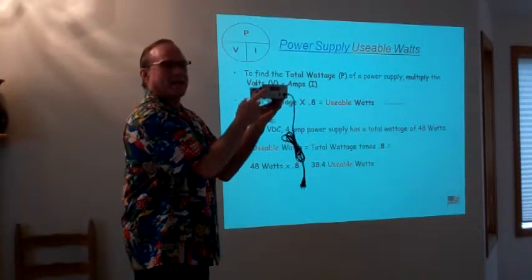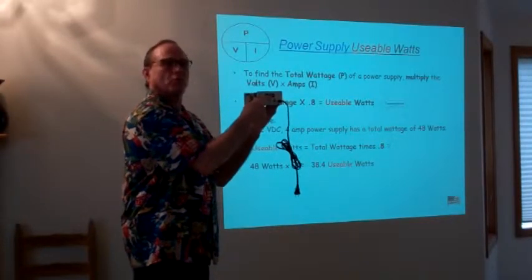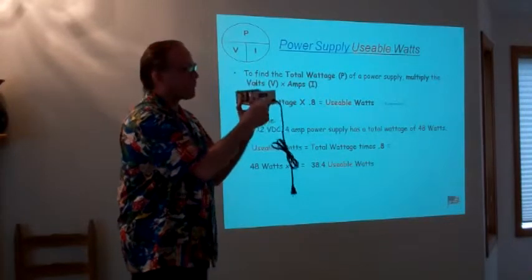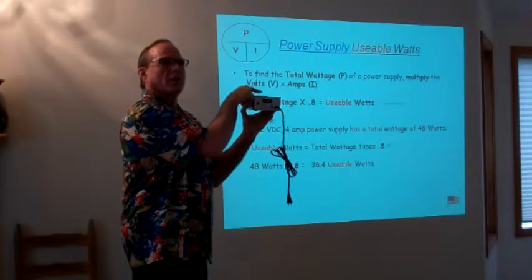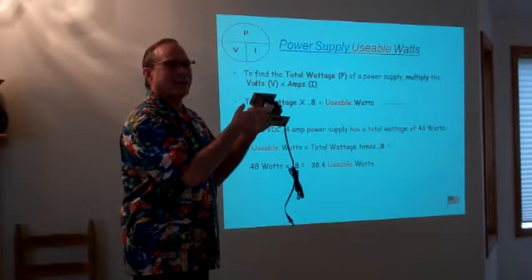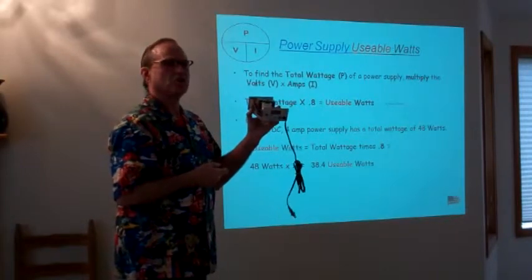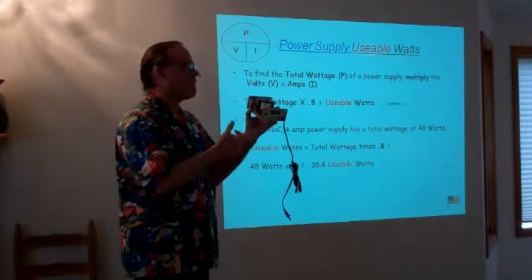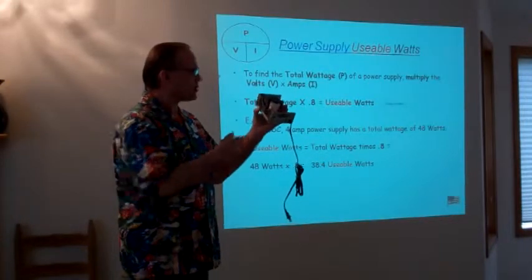If you don't have that in there, you would continue to have your output still drawing, and the level of heat that would be developed here, because as we start developing more current, would start to overheat all the components inside the actual power supply. Eventually it would get so hot that the actual windings and so on would short out. You would burn up the power supply, in other words. It wouldn't catch fire necessarily, but you most assuredly would shorten its life by far or completely destroy the transformer.